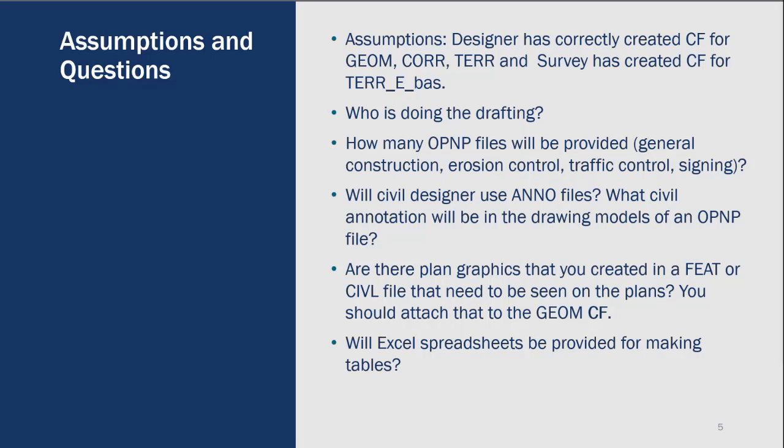Who is actually doing the drafting? And is it going to be your CAD technician on all aspects, or are you going to share that? How many plan and profile files, OP&P files, will need to be provided? Do you have detours on the job? Well, you'll probably need a separate OP&P file for detours, separate from your general construction.